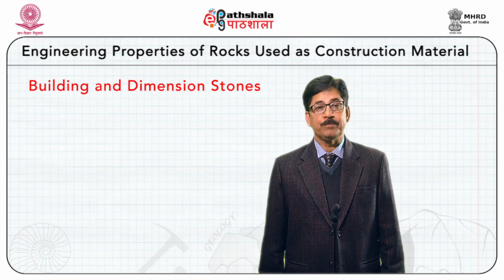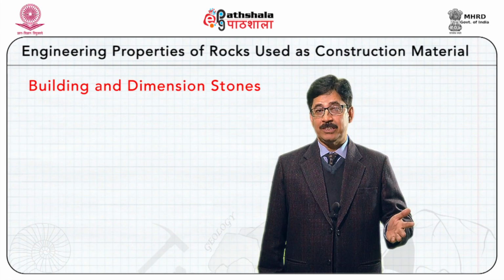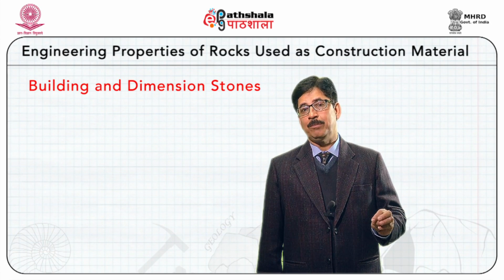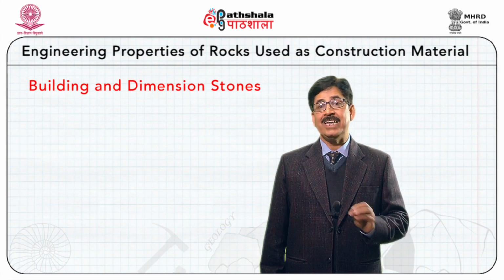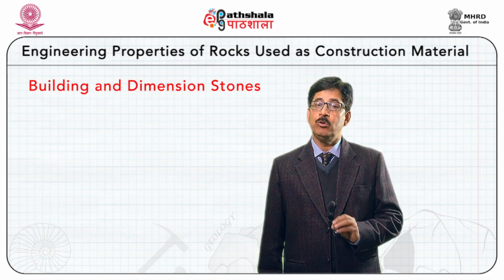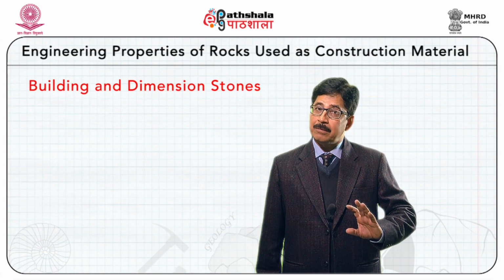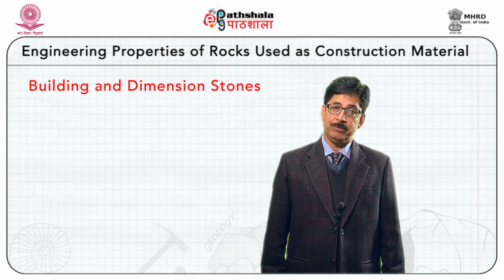because we don't want any rocks which can add frosting. All porous rocks will add frosting, but non-porous rock will be free from the problem of frosting. As far as fire resistance is concerned, it has been found that rocks which are monomineralic fare better in terms of fire as compared to the rocks which are polymineralic.